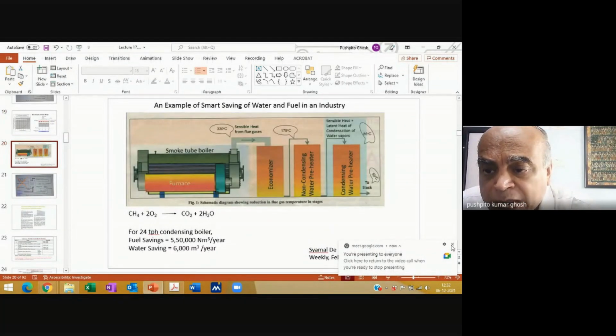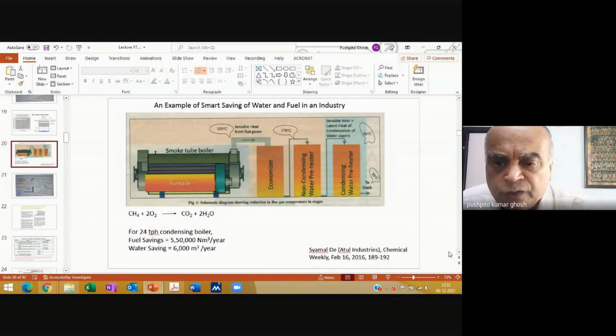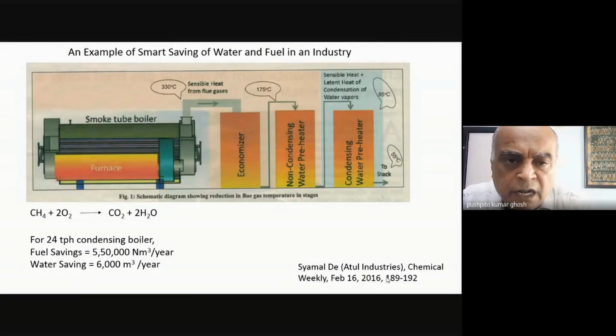We talked about also that water can be produced in a reaction. For example, if you are operating a boiler and using natural gas as your fuel, what will happen? The natural gas is burning and forming carbon dioxide and water, and natural gas is quite pure, just methane. There's nothing else there. Whereas if I had heated it with coal or something, there would be a lot of impurities. But here it isn't, and quite a substantial amount of water is being formed. From 16 grams of methane, I end up getting 36 grams of water.